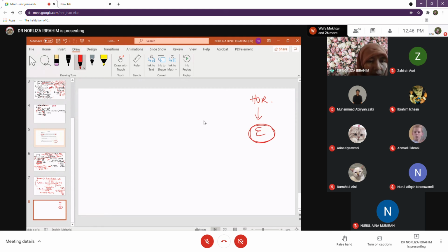We go to SO3, because the SO3 flow rate is already given. SO3 in the product equals SO3 in the feed plus extent of reaction. In the product you have 1500, in the feed 0 because you do not feed SO3. SO3 is your product. So your extent of reaction is 1500 mole per minute.